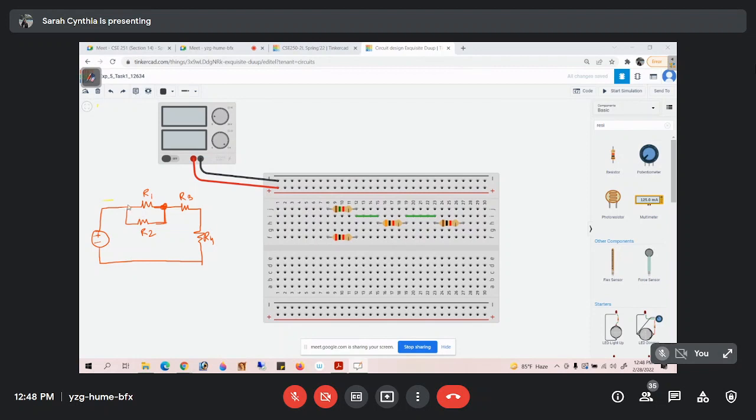This particular node, that is R1 and R2, the first terminal of R1 and R2, is connected to the positive terminal of the battery, right? So this column, that is column 8, we can drag a wire from this column 8 and connect it to the positive terminal of the power supply, since column 8 is basically the node of R1 and R2. Do we all understand? Yes, ma'am.